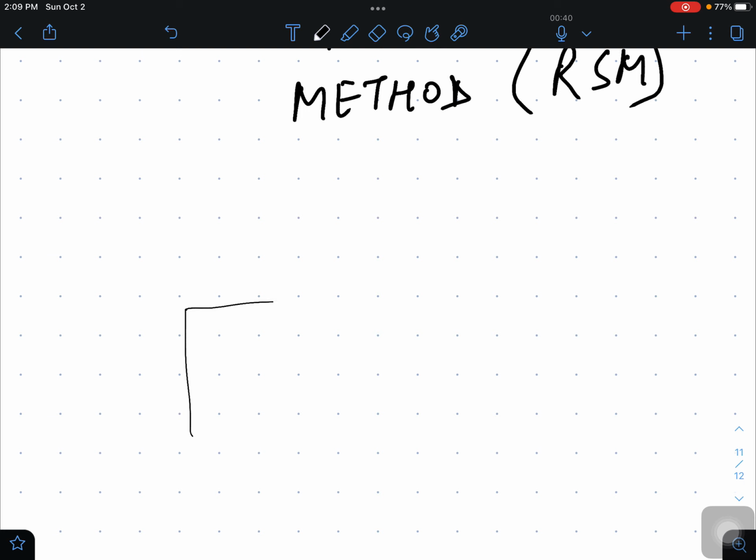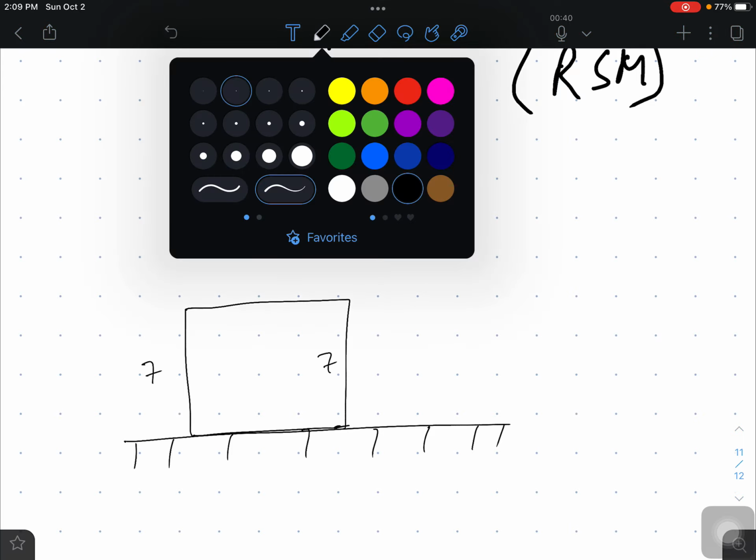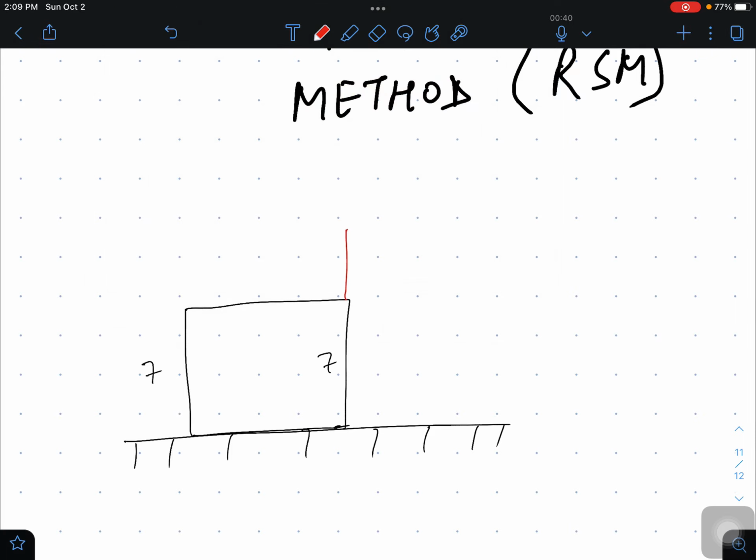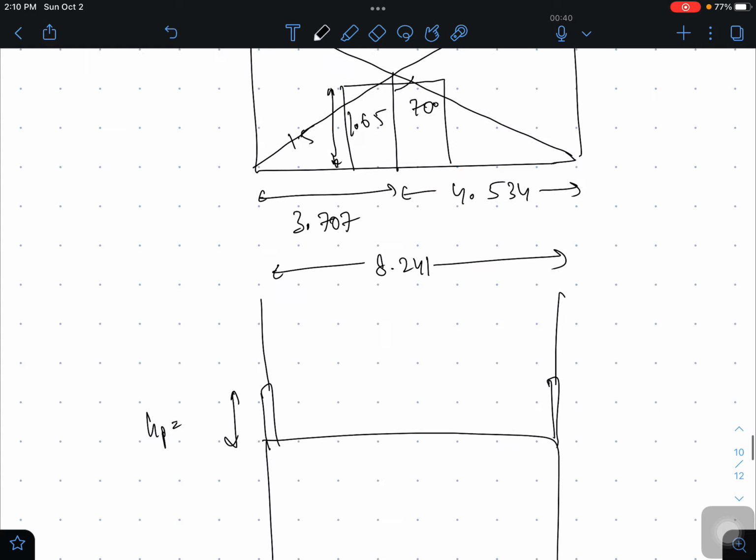So this is our building which we saw the last time, and this is our reference, our mother earth. Then this is 7 meters long, and then we have an air terminal rod which was 3 meters in height. Now as we have used class 2, please note that we will use class 2 only here. As per class 2, the rolling sphere has a radius of 30 meters, which is available in IEC 62305-3.